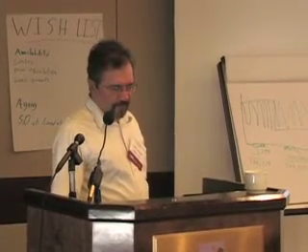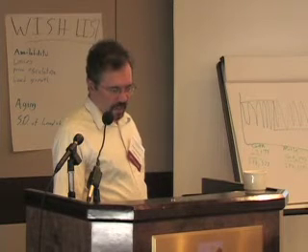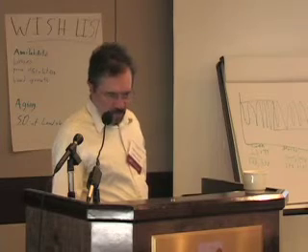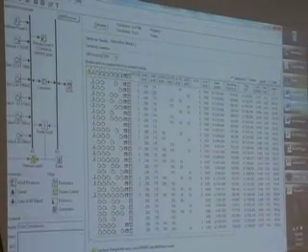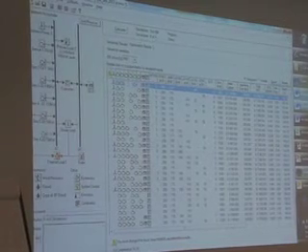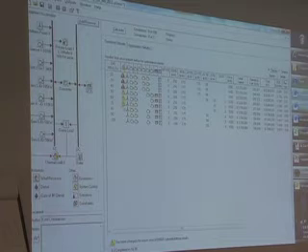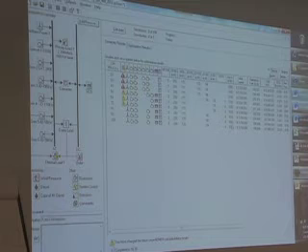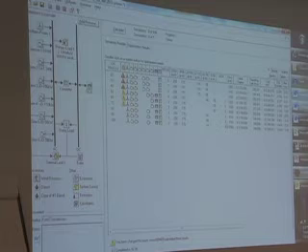Now if we go, that's adding 1 turbine? 3 turbines, oh, 3 turbines, which is right here. And an electric boiler. 3 turbines, an electric boiler, 6 flywheels. So let's come over here. This is a better way to look at it. So at 100% operating reserve requirement, we need 6 flywheels. If we lower the operating reserve requirement, we need fewer flywheels.